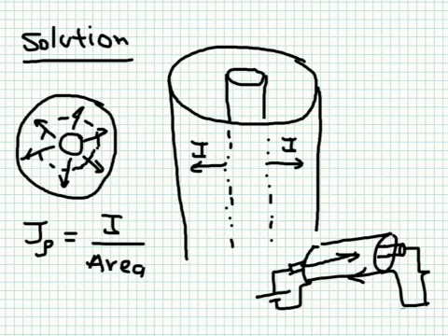No, there will also be a current flowing radially from the inner conductor to the outer conductor, because these two conductors have a voltage difference between them. This is really an undesired current. This is a leakage current. We usually don't want it, but it does exist because the insulator does not have infinite resistivity. It has some conductivity. The conductivity should ideally be 0.